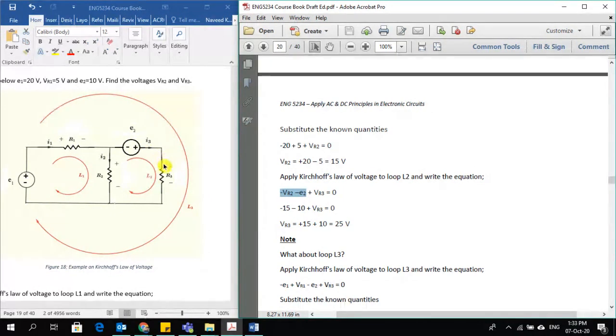Then moving along, I come across this resistor R3 with positive polarity first. I saw its positive side first. So I will write voltage on this as plus VR3. So plus VR3 is written here. So this is my equation. There is no other component, no fourth component, only three. So I will just write all three equals 0. So this is my Kirchhoff's voltage equation for loop 2.